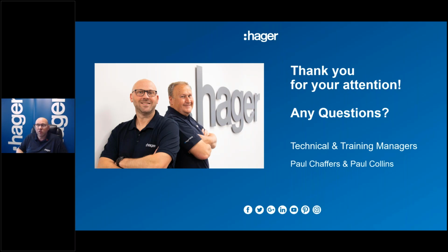So the question about going outside doesn't really fall under the intent of 421.1.201, although there's nothing to preclude the use of metal outside, but of course it would need to be suitably rated for the external influences that are present outside. That's why most people would generally use a plastic consumer unit with a suitable IP rating.